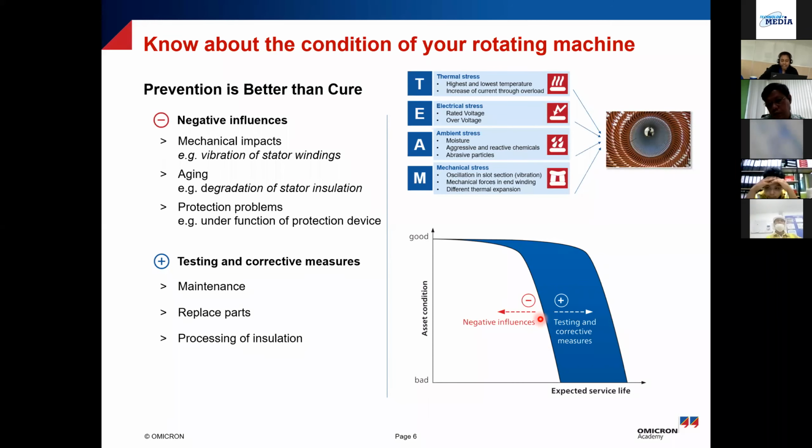in the sense that you have major overhauling periods. Some tests can be done only then. You have some limited inspection periods. So in that scenario, you can actually conduct only a certain number of tests because in some tests, you need the rotor out. So careful planning of all your test requirements, and then subsequently getting immediate results so that something can be done. So let's say you identify a problem during a major overhaul, and if you have to wait for analysis, then you might not be able to correct it.